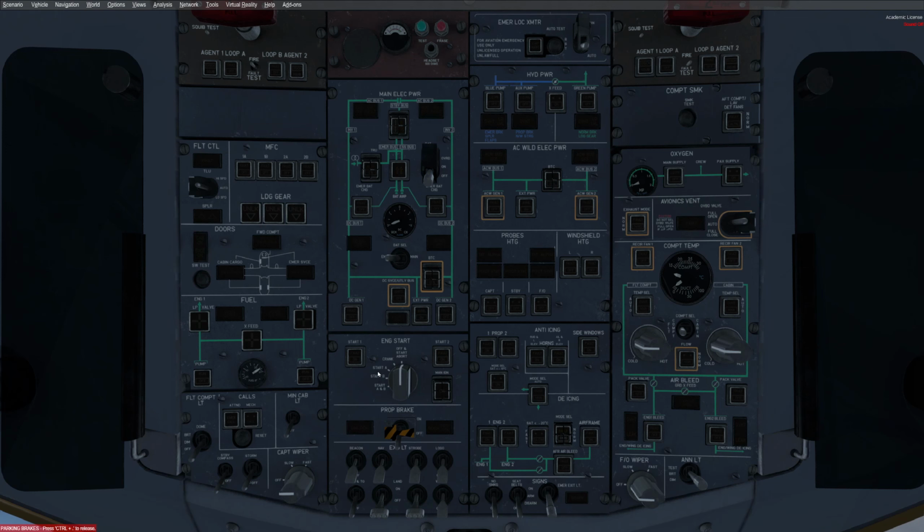Oh, the engine starts, you'll be normally putting it over here. Here's your start 1, start 2, and the pumps for the fuel on either side for each engine. Over here it'll be oxygen main supply, passenger supply, the avionics vent, leave it on auto. This is to cool off the avionics with exterior air. There's a little vent, I believe, at the belly of the aircraft. If there was a fault, then you could manually fiddle with it, but we don't expect to do that.